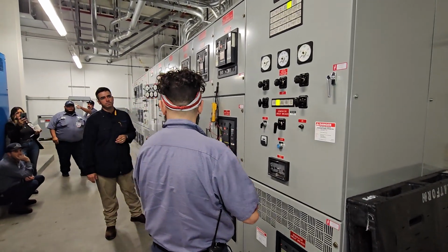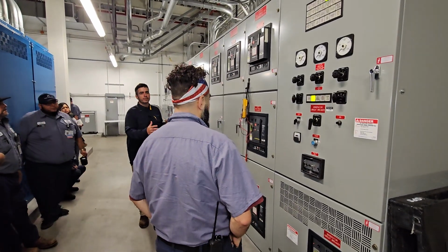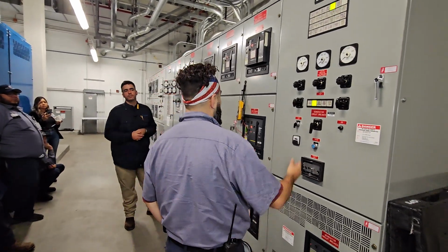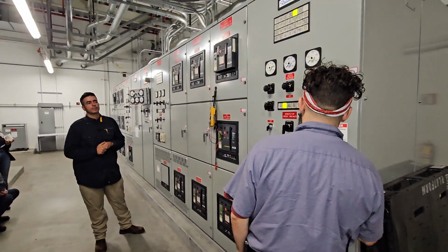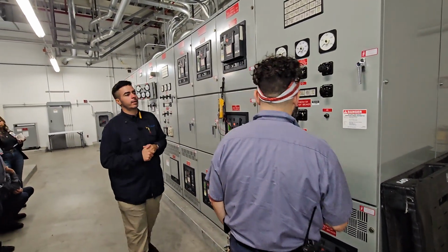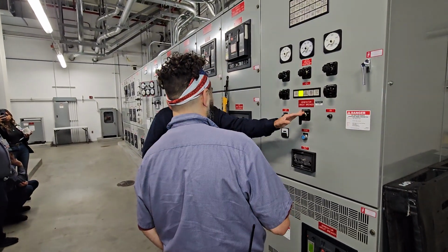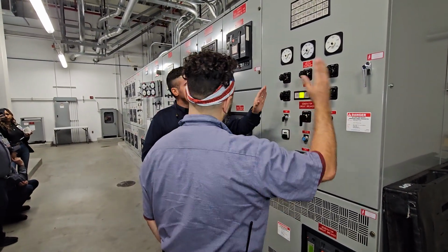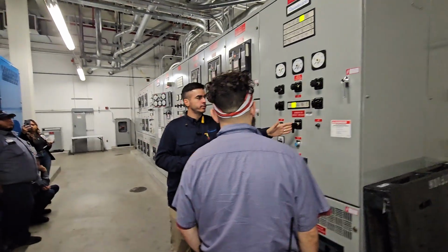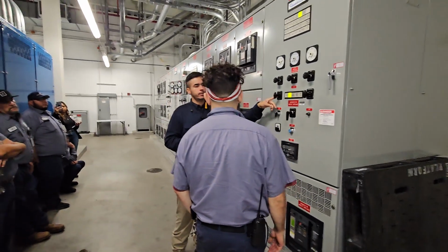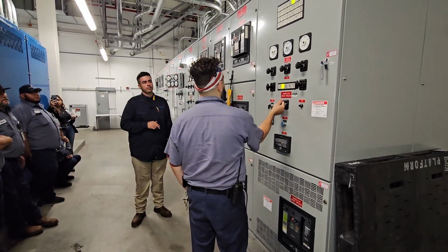I thought the next step was to sync. What do I gotta do to bring this up? Well, there is nothing to sync to, right? Because right now you only have one gen. So I just have to. Which one puts it on the bus? Like puts the power on the bus, I guess. Okay, so you got a breaker control here, right? So you want to close the breaker, you have to take it to close. And that'll put it on the bus. Yeah, the only condition that you can try, but if this one is not on, it's not gonna do it. Okay. Go ahead and try. I'll try it. Yeah, that's it.